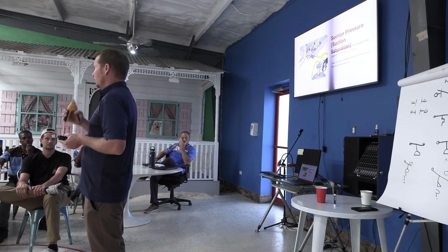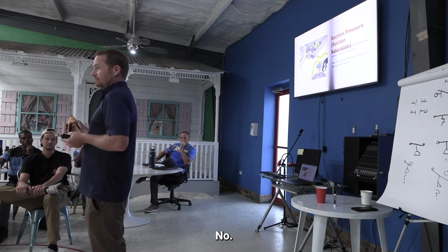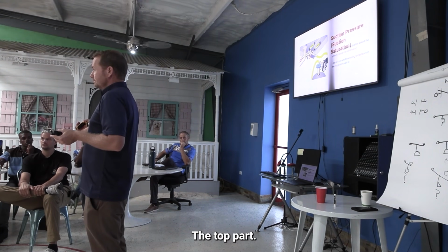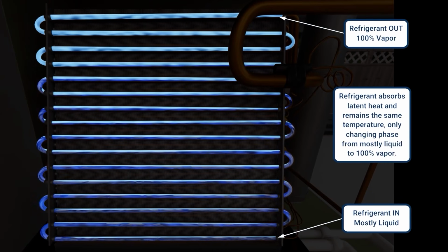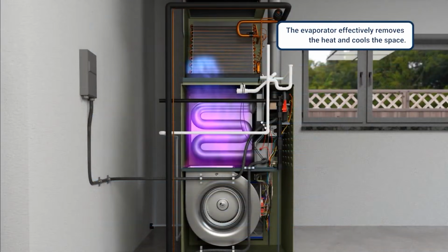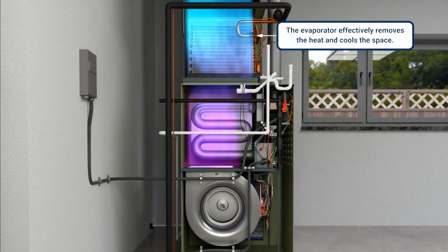Now here's the trick. Is that entire evaporator coil 35 degrees? No. What part isn't 35 degrees in the evaporator? The last part, right? The top part, right? So you feed it in the bottom. You feed this saturated, boiling refrigerant. I always wish they would call evaporators boilerators. I think that would be cooler, and that's actually more accurate about what's going on. The refrigerant's actually boiling in that evaporator coil. You have boiling refrigerant in the bottom, and it boils until it gets to the top, and hopefully the last little bit is fully vapor. And whatever temperature's picked up in that vapor, that's what we call superheat, right?